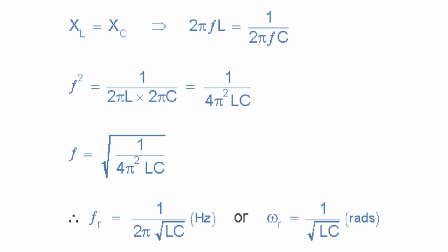The resonance frequency of an AC circuit is the frequency at which the XC and XL are equal in magnitude but opposite in phase, causing them to cancel each other out. At this frequency, the circuit exhibits purely resistive impedance, leading to maximum current flow and minimal impedance.